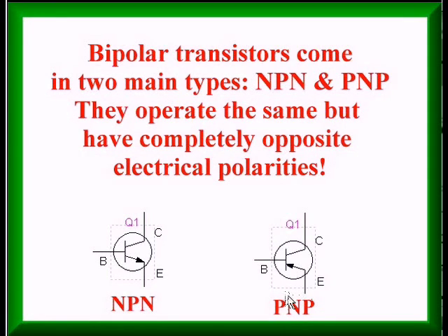That is, you need a negative voltage on the base with respect to the emitter. This will produce a current when it forward biases the PN junction. The amount of current flowing through the base to emitter or emitter to base, either way you want to look at it, is multiplied by HFE to give me an emitter to collector current.